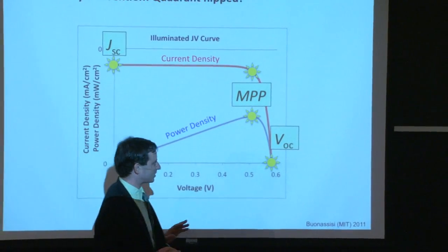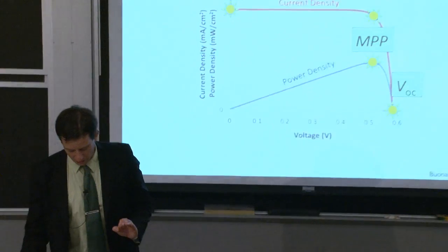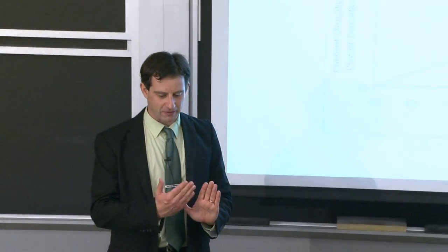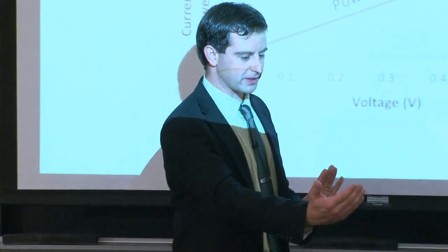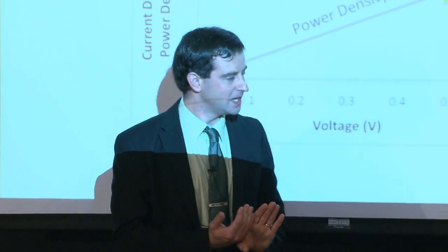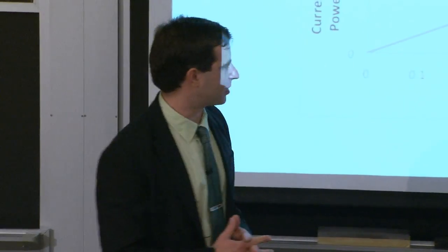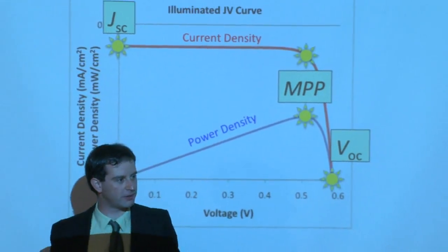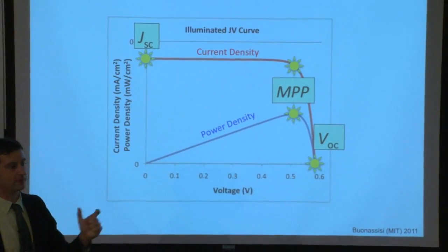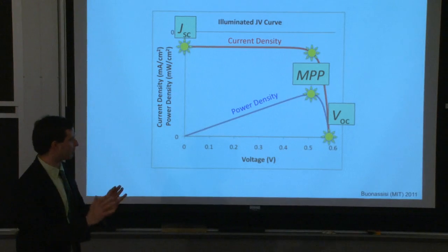The last homework had one question that said, assume that the voltage at the maximum power point is the band gap voltage equivalent minus 0.5 volts. And the rationale for that assumption is as follows. The open circuit voltage, this point, is generally between 0.35 and 0.4 volts lower than the band gap. So you have the band gap energy minus 0.4 volts.